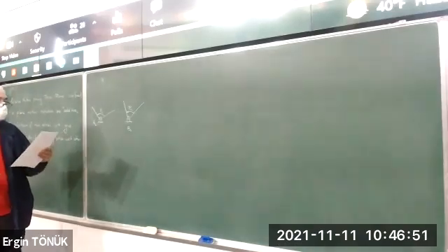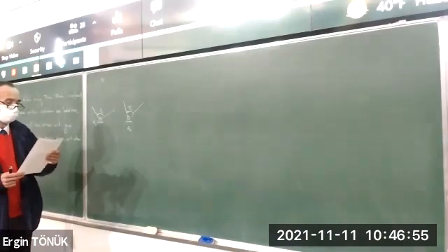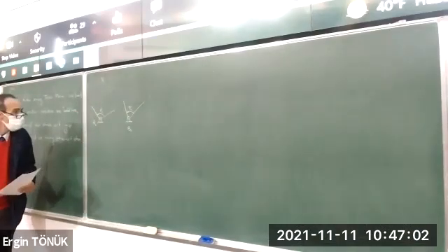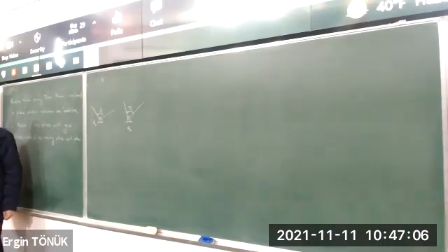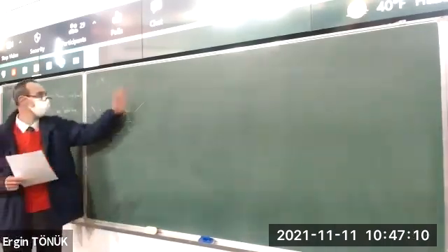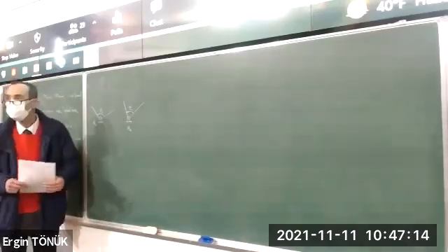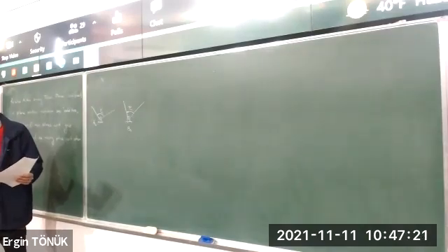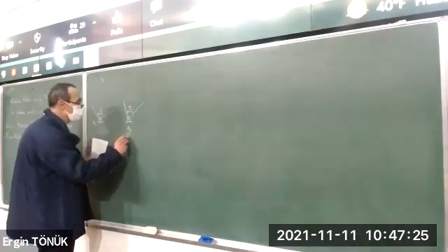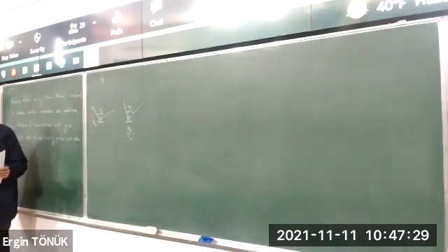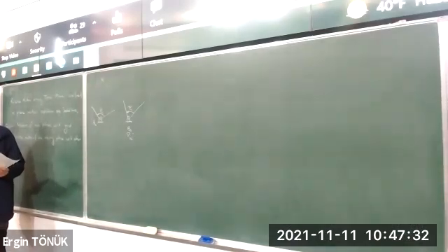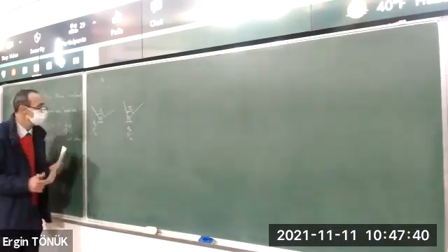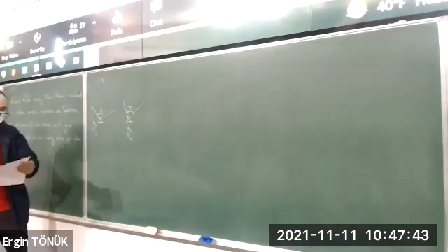So, to find the relative pole, we have a procedure. We know how much they rotate and where the poles of these two motions are. I'm rotating this from here to there. Where is the pole? Yeah, that's it. It's making fixed axis rotation, so it's always the pole, or it's always the instant center as well. So I'm going to call that P12 prime. This time prime is not standing for inverted motion. We have nothing inverted, okay? So the notation is not all consistent. And this is P12. So P12 is for this crank, P12 prime is this crank.